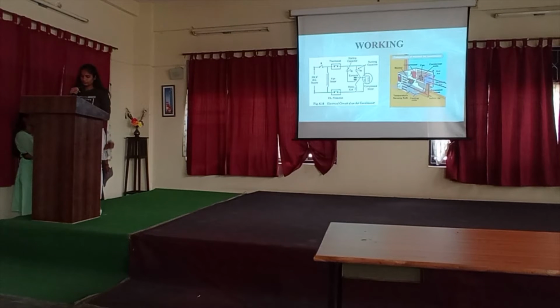As the motor gradually reaches normal speed, the current in the running winding decreases, making the relay open, thus disconnecting the supply to the starting winding of the motor. The overload protector protects the motor against excessive overload. This protection is provided inside the compressor, and its function is to open the compressor motor circuit.